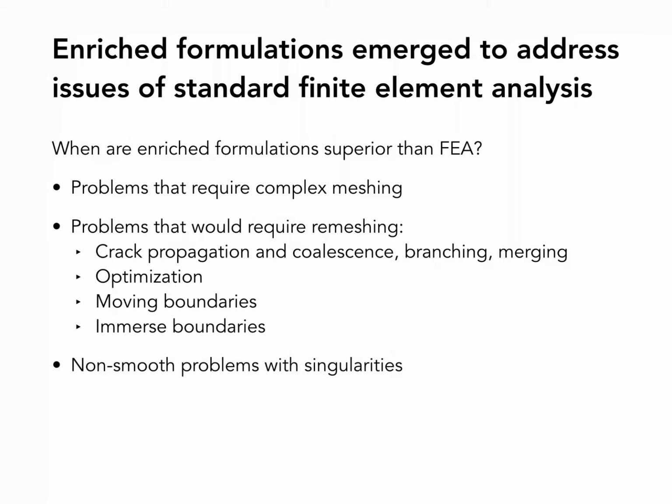I'm sorry, what does it mean, immersed boundaries? Immersed boundaries. So imagine you have an object, and you want to find a solution to a boundary value problem. So you have your equation, let's say your equilibrium equation and boundary conditions. This forms your boundary value problem, and you want to solve that problem. Of course, one way to do it is to get the object and create a conforming mesh, or a matching mesh. So the sides of the elements are basically aligned with your object.